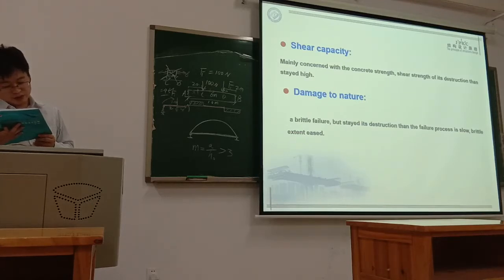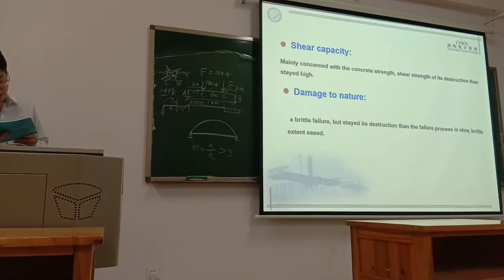The shear span ratio is between 1 and 3. With the increase of the load, several diagonal cracks come into being, and one of them develops into the critical inclined crack. After the critical inclined crack appears, the beam still works until the concrete at the top of the crack is eventually crushed. So the shear capacity is related to the size of the cross section, the concrete strength, and the spacing and the strength of the stirrup.